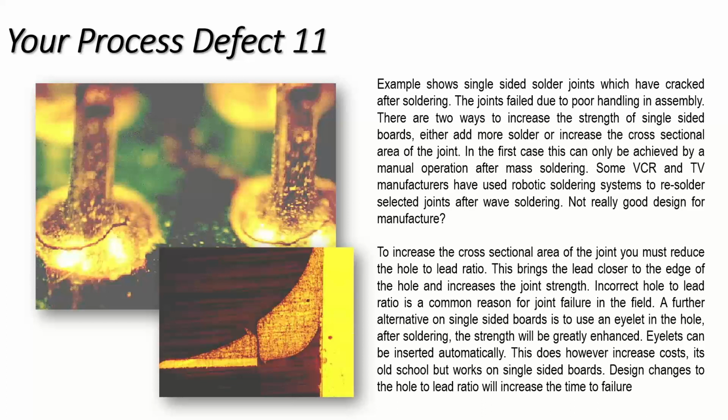But if you need longer longevity, or you've got very heavy components which are subject to drop, shock, vibration, then eyelets might be an option for you. You can obviously go to plated through hole boards, but that will have quite a significant impact on the cost of the printed circuit board for your process. Okay, so that's a few defects that I've gone through.